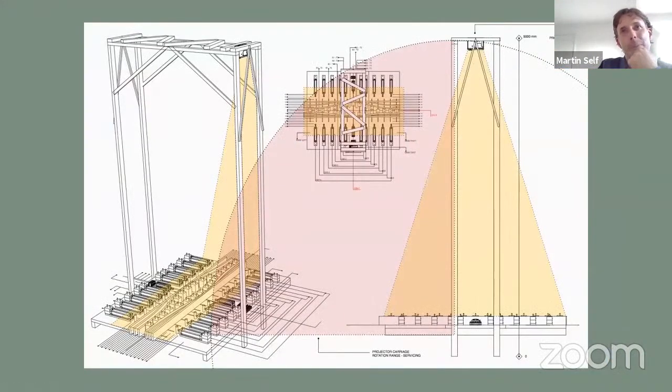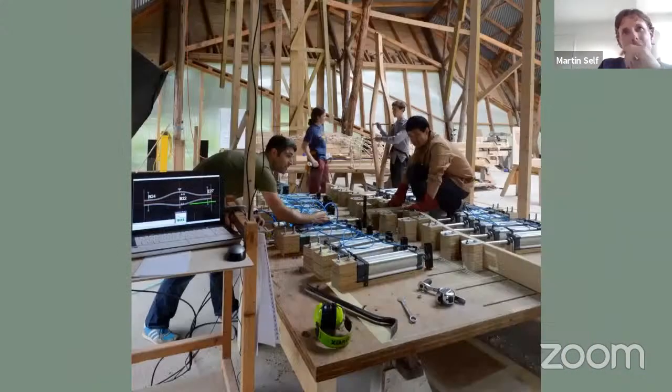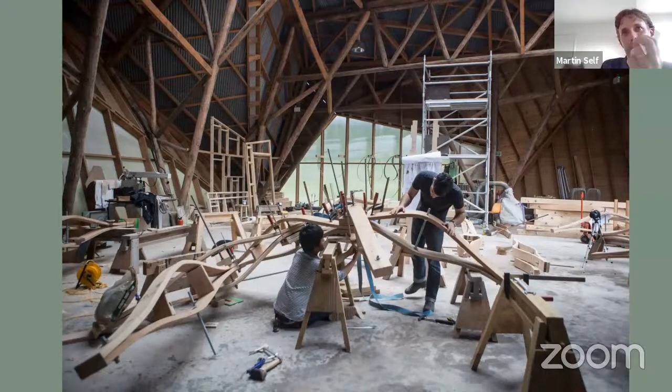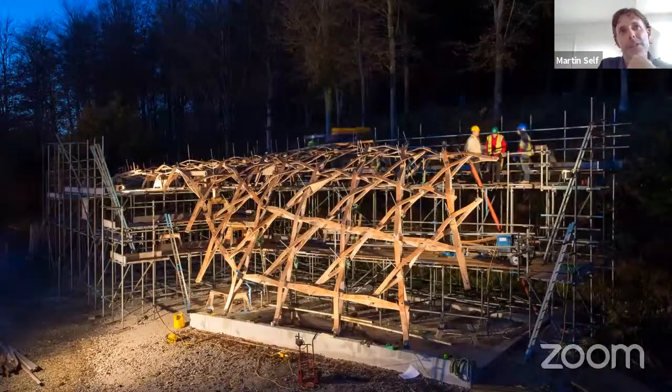So students invented big bending jigs, a semi-digitalised process, where a digital model was projected and mapped onto the bending jig. There were lots of strategies for how you allow the pieces to dry and not creep, and then pre-assembling patches of this structure that then came together in this shelter for the future air drying of timber.